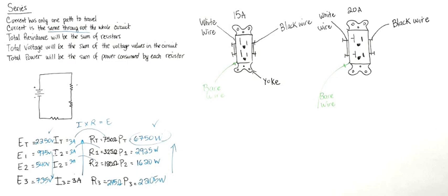Some electricians, for example linemen, work with power. They can't shut off the power for the city when they're connecting, disconnecting, fixing something that's broken, or giving maintenance. What they do is use specialty tools and specialty gloves, and they're trained how to handle all the wires and make themselves at the same potential as the system they're working with, so that they don't close the circuit or become part of the circuit, right? This is something they train because they're working on live circuits.